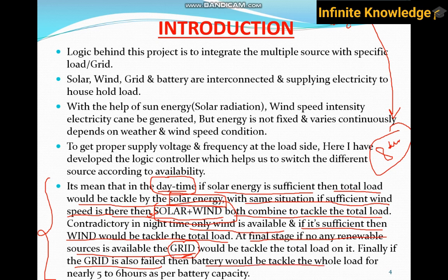The battery would tackle the total load for 5 to 6 hours as per its rated capacity. I have designed one battery of 100 ampere hour, so it would take nearly 5 to 6 hours if there is no other source. The battery single-handedly tackles the whole 8 kilowatt load for 5 to 6 hours. Okay, so this is how you can design the system.